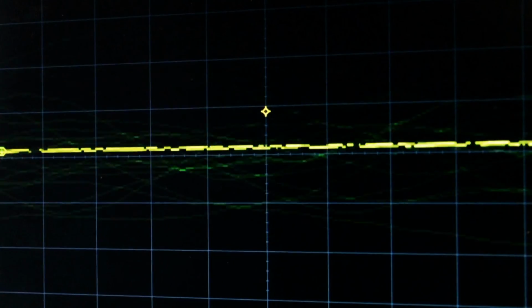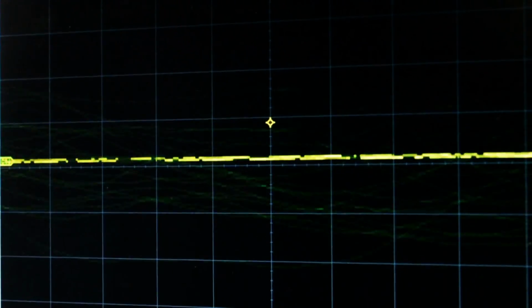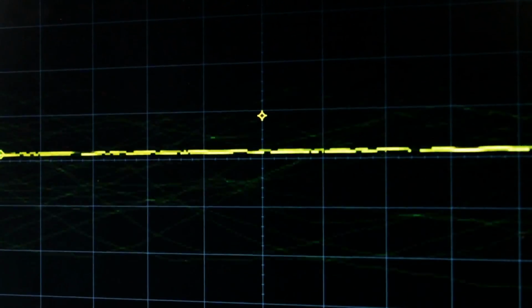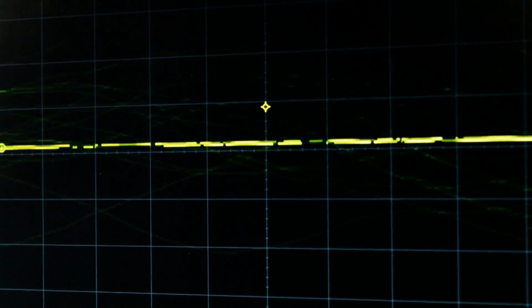Noise can provide a voltage offset that will produce adverse analog or digital outputs from the sensors onto the microcontroller. Additionally, restrictions from the microcontroller, such as voltage capacity in each pin, would have to be accounted for. The tracking subsystem is responsible for receiving meteorological and GPS data from the weather balloon post-launch.